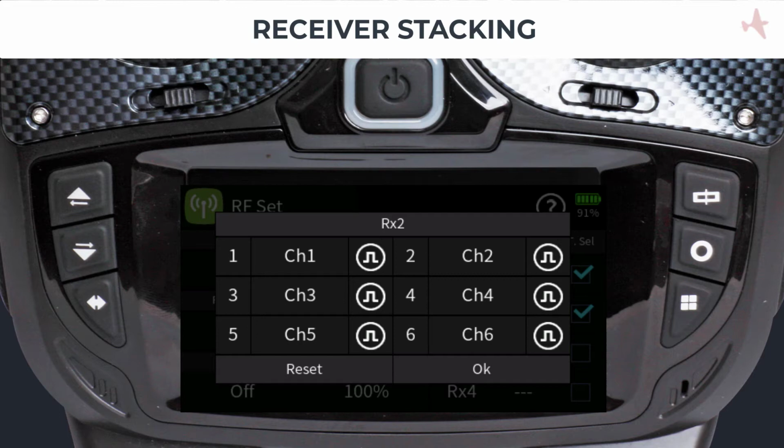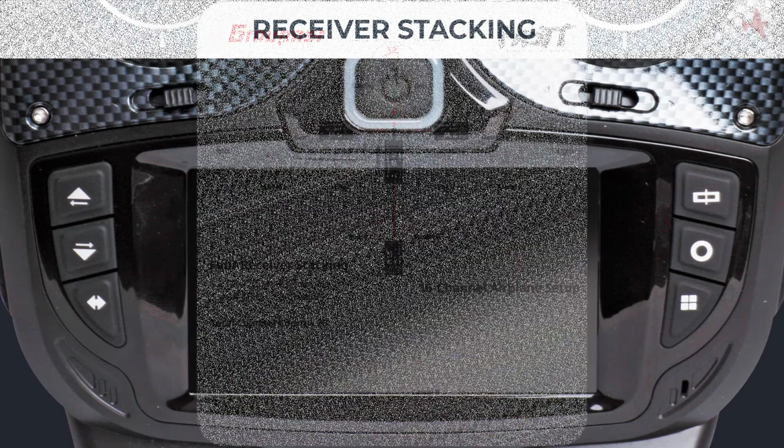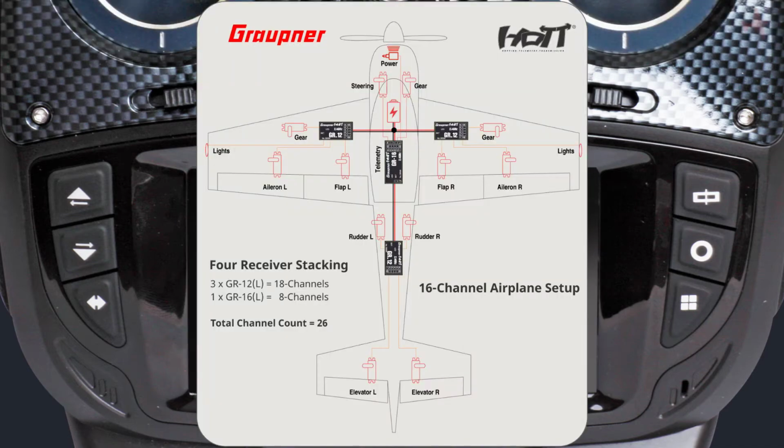Stacking receivers can assist you with simplifying your installations, providing a more manageable and better scalable model setup. This example uses 4 receivers to set up an airplane to control 16 channels. We use a single receiver in each wing to directly control ailerons, flaps, landing gear, and navigation lights. The only wiring coming from the fuselage are the power wires to power the receiver.